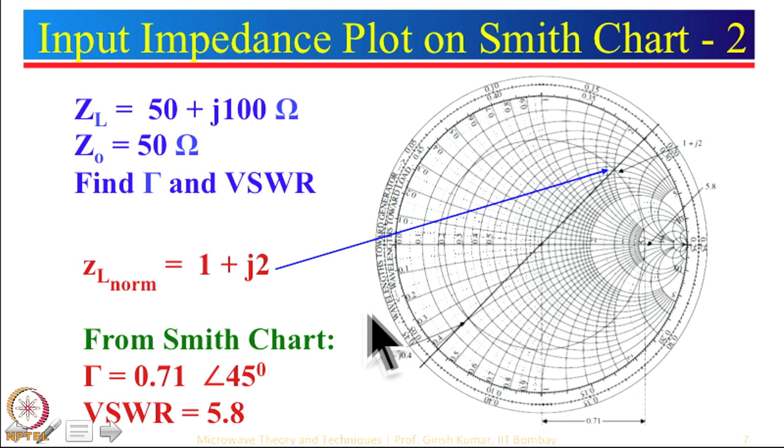I have shown you different types of Smith chart, so that you know, depending upon what is available to you, but this one here is relatively better to look at for locating the points, because it has a much larger number of circles. So, let us see here what you do. You locate 1. So, 1 will be the center point, and then we have a plus. You move in the direction above, and there you stop at a point where this curve corresponds to j2.